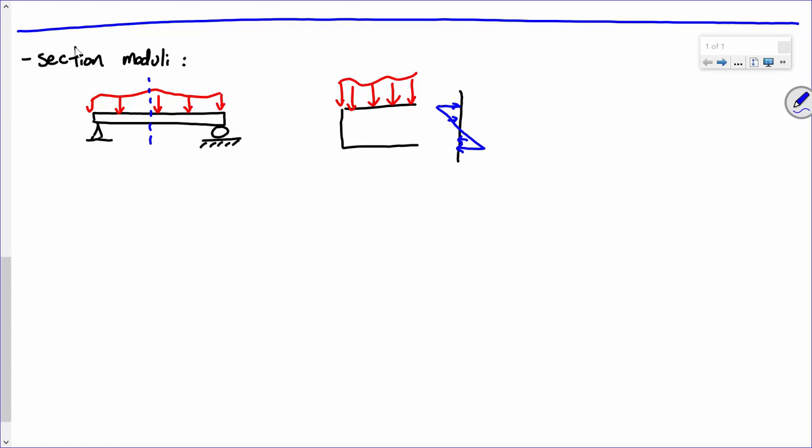That should be back from basic mechanics, strength of materials, mechanics of deformable bodies, whatever the class was called, wherever you took it. This is just basic stress analysis. I have a beam, it is being bent. How do I characterize that stress? I characterize it with the formula sigma equals My over I. Y'all remember that, right? Okay.